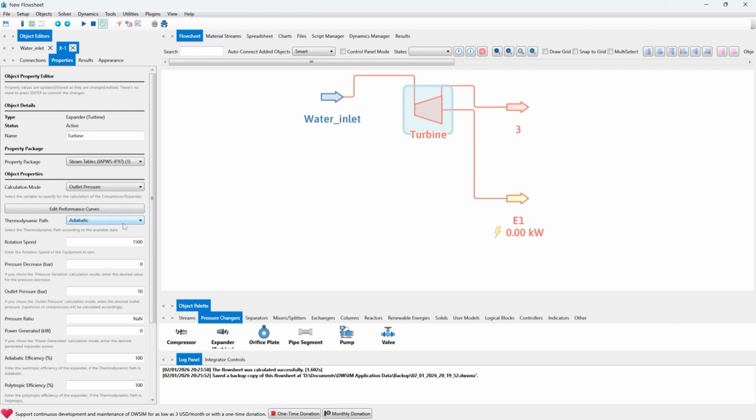In such software, it treats a turbine as one component. The fans, the shaft, everything is treated as one component, and it is actually simpler to calculate because it is discrete. It takes just specific chunks. In our case, we have just one turbine, and we do not know the stages inside the turbine, so we're going to use adiabatic.